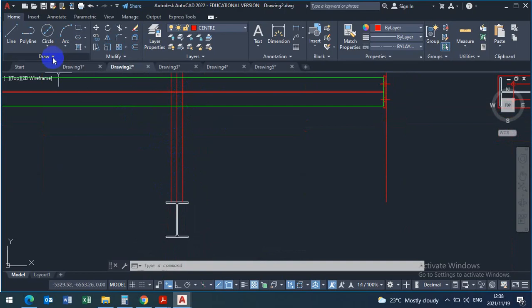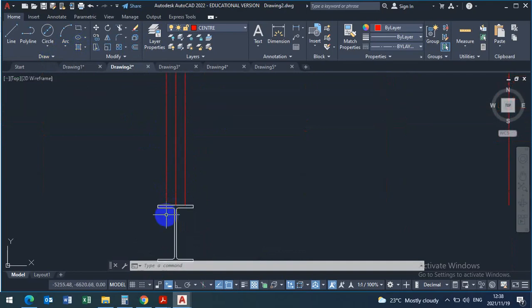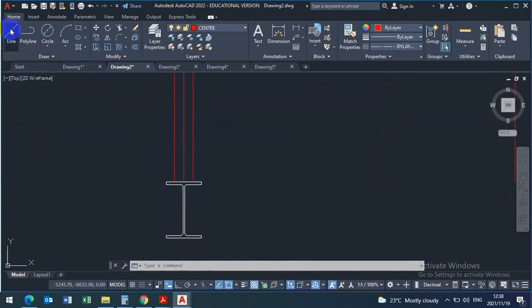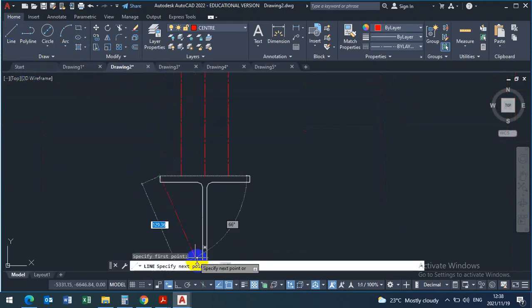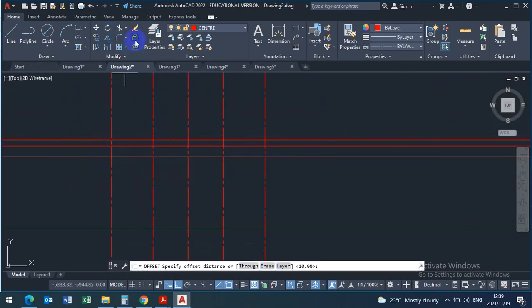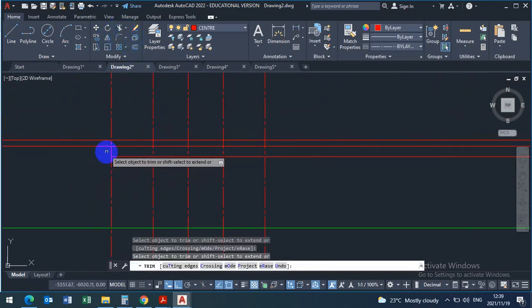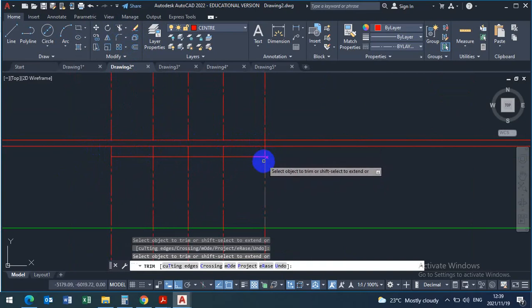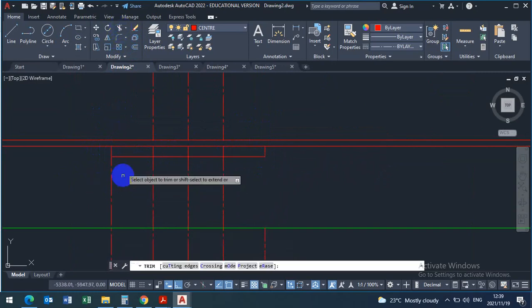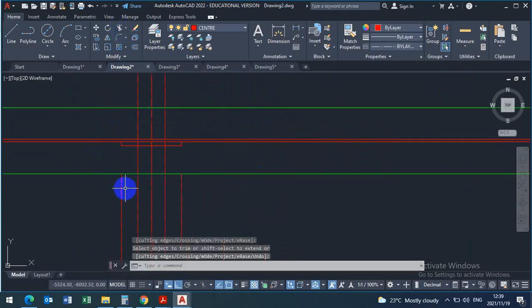Okay, when it's coming, though, we don't need to show that part of the beam. It will be part of beam 3. Beam 3 will have its own end plate, which means it will be going here. Let's say that's the thickness of the plate, and then you trim. The plate will be trimmed somewhere here, here, here. You see the way I'm trimming? There, there. That will be the end plate that will come with beam 3 to be welded on the web of beam 1.